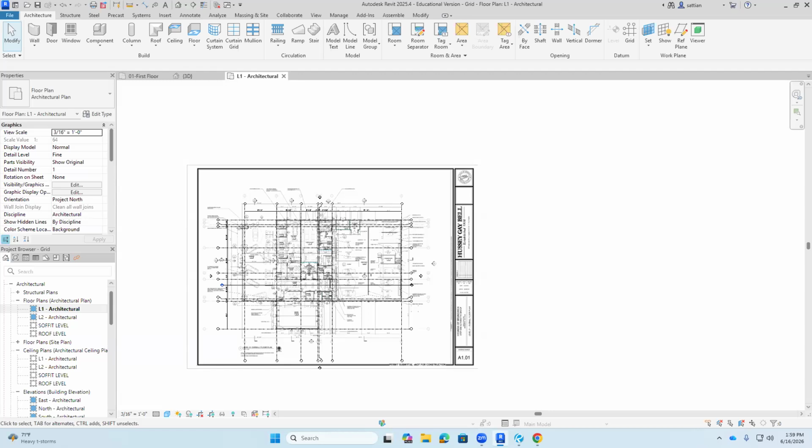It may not actually, this one too. This one may go all the way to the ceiling because that room is also a classroom, so we don't want sound to go back and forth. But office spaces, for instance, on the opposite side, the wall doesn't go above the ceiling. Now that wall will go all the way to the ceiling. The reason it goes all the way to the ceiling is fire safety, right? Anytime there's a fire, we want to isolate areas so that we give people enough time to get out of the building.